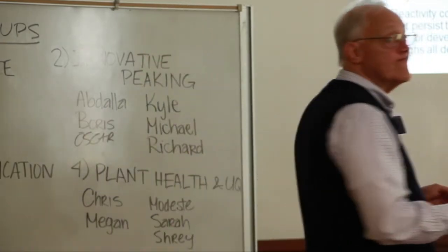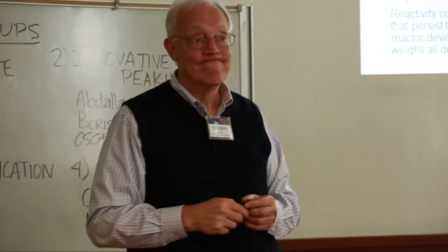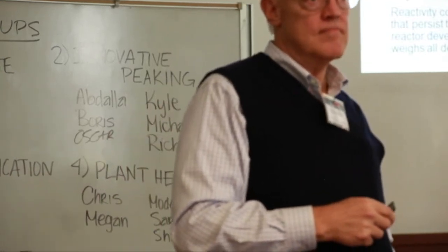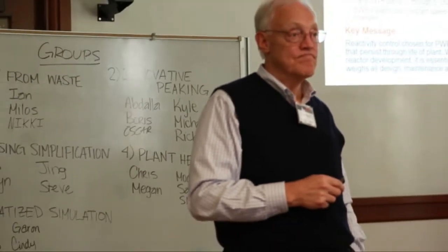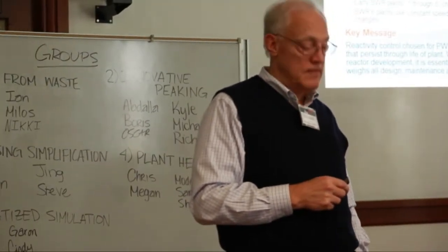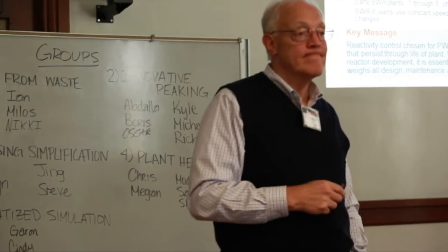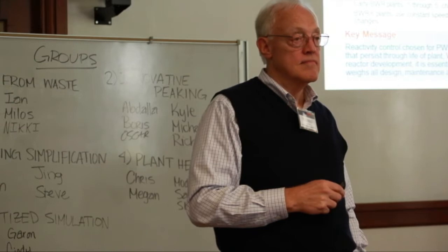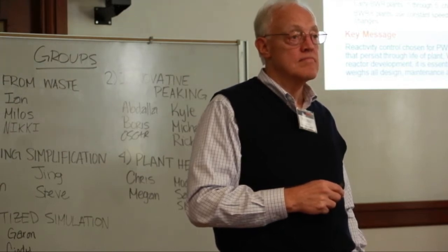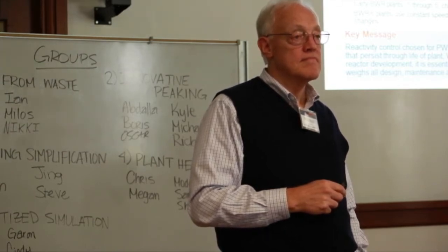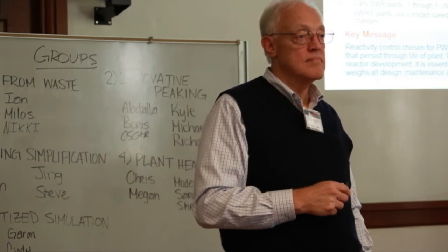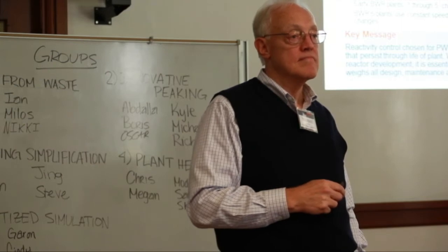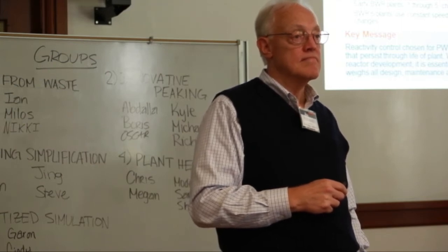Can I just add a comment on that? I think the other thing to bear in mind is that one thing boron gives you is the ability to change your operations after you've started the core. That's correct. Whereas with thermal poisons, you have to make that decision at the design stage, and you're committed. So the global reactivity can be changed with boron. Once you're operating a commercial reactor, unlike a Navy reactor, the power needs go up and down, and boron allows you to make those changes.